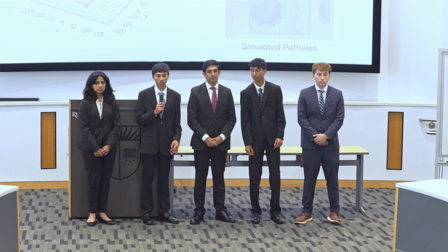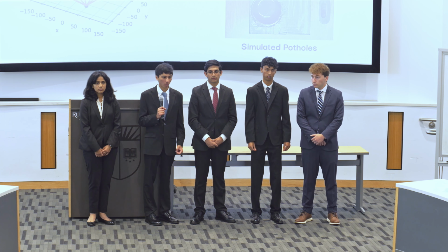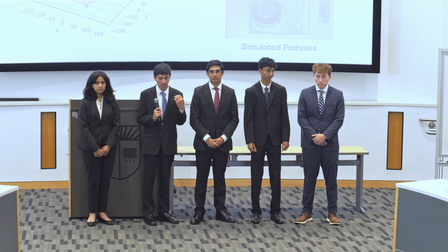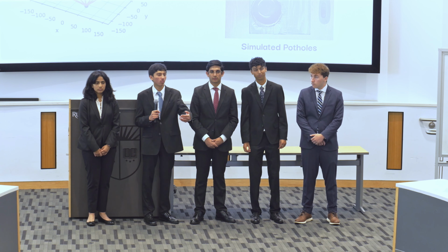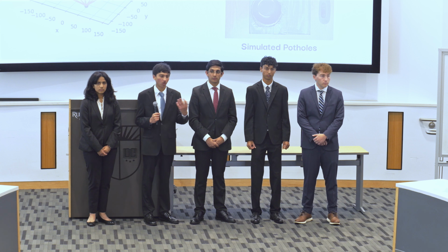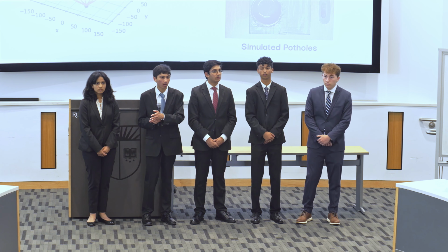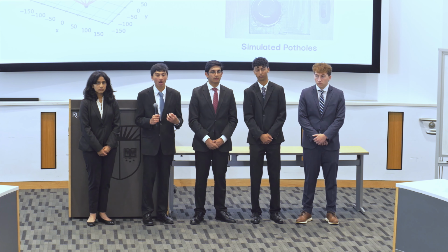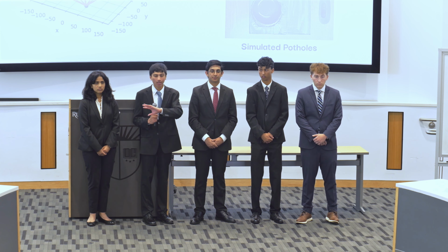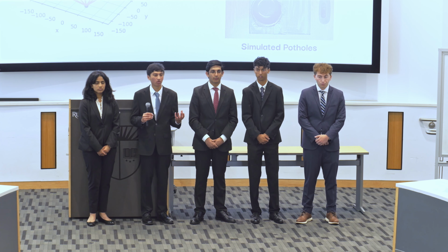Just like Aarav mentioned, once we detected the pothole, we were able to get the volume of the pothole. How we did this is that the LiDAR sensor would be in constant motion at a roughly constant velocity on a car or on the vehicle that we would be mounting it to. From there, we can generate hundreds of angled planes per second and use trigonometry to essentially get them out to a 3D map, essentially combining hundreds of 2D planes into one 3D plane.